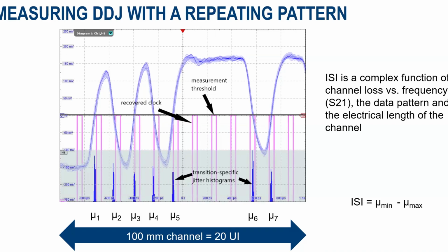It can be done using software. It can be done using clock recovery methods, or even special triggers, or even by supplying a pattern clock to the instrument. However it's done, you want to make sure that you're locked into the pattern so that every time the same bit in the pattern comes around, you can compute or measure its crossing time.